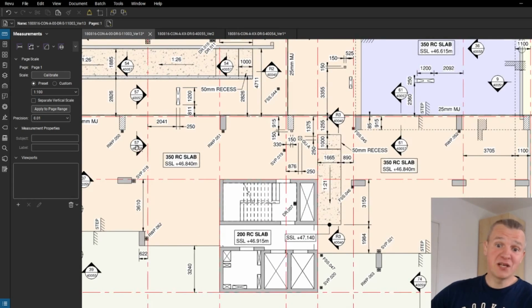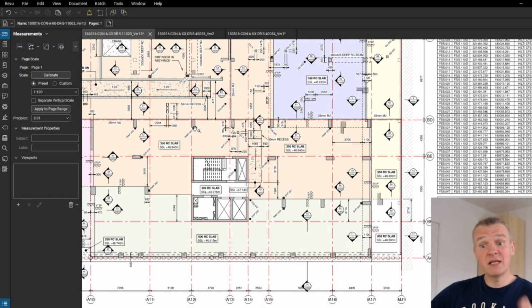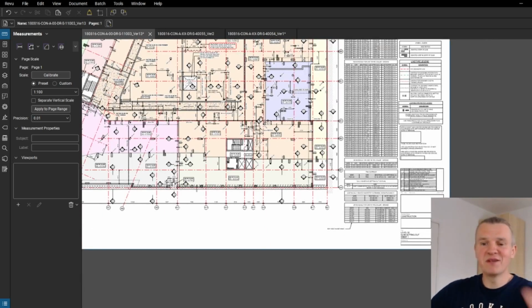And then we go to the sections, and if we are confused or need some more information, we're going to find that information on the sections drawing. And that's the way you should go about it. First check if it's for construction, then go through all the information on the drawing, through the legend, through everything, then check the levels if everything is correct, and then have a look at the other drawings and the sections, which will then complete all your knowledge about this particular slab in this case, or about the particular building.